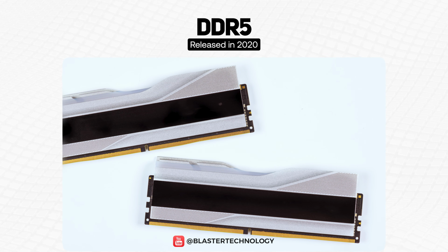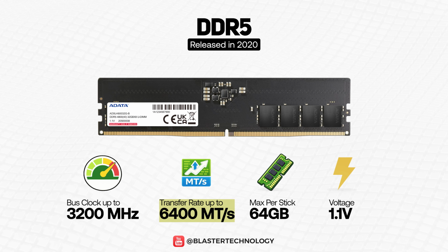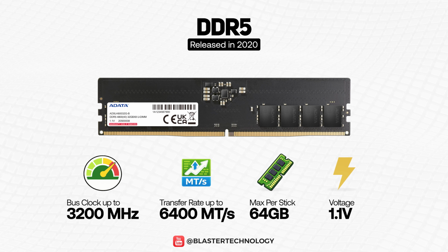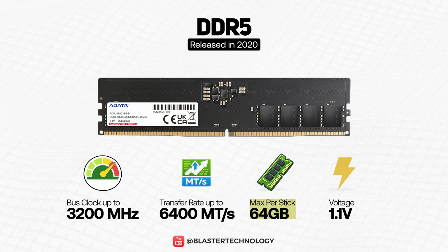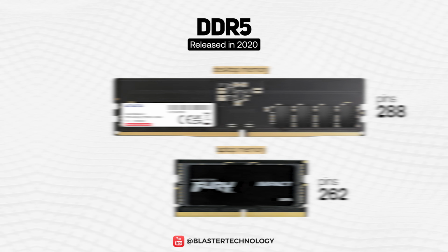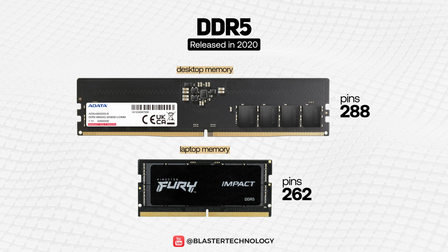DDR5 was introduced in the year 2020 and changed the internal architecture of system memory. With a bus clock of up to 3200 MHz and a data rate of up to 6400 megatransfers per second, DDR5 is the fastest memory generation currently available for mainstream consumer systems. For consumer desktops, the maximum capacity goes up to 64 GB per stick, while the operating voltage was reduced to 1.1 volts. For desktop systems, DDR5 modules use 288 pins, and for laptops, they use 262 pins.